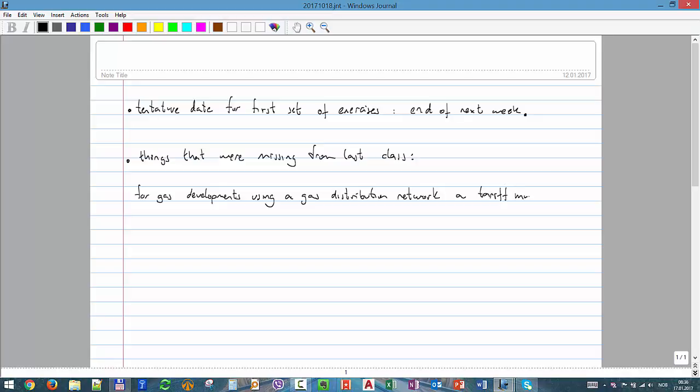A tariff must be paid. Okay, in Norway it is Gassco. And that's after I have processed my gas, so that it already meets the requirements they have for this gas. Okay, it must have almost no liquid, must have a certain dew point, must have a certain content of CO2, very similar to the gas specs, to be allowed to be transported in this system.